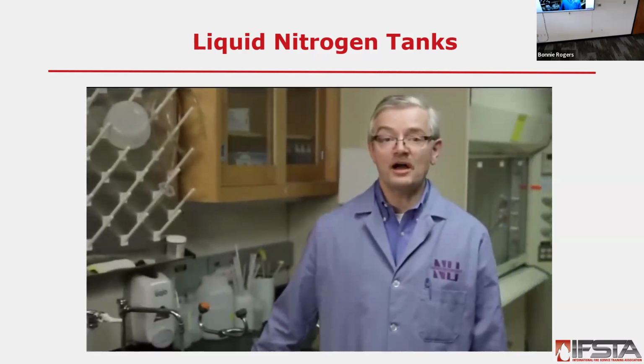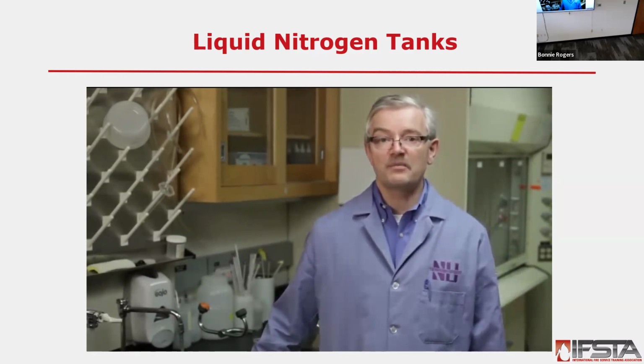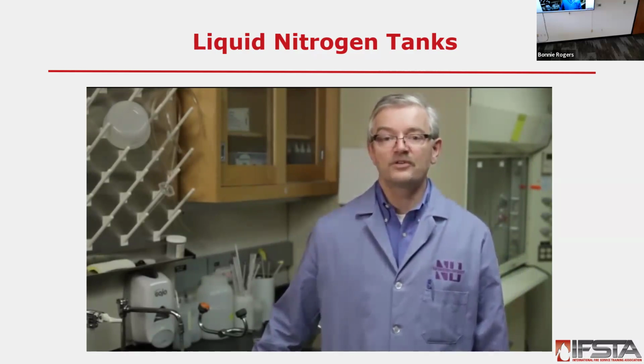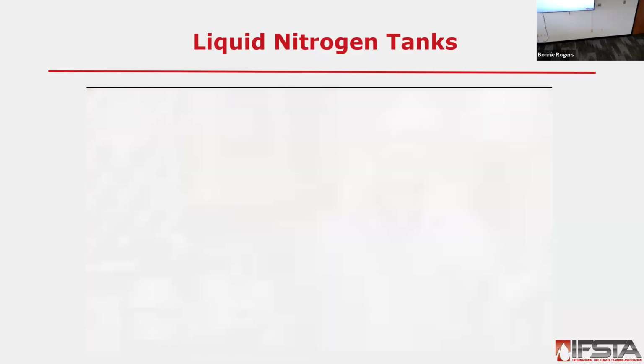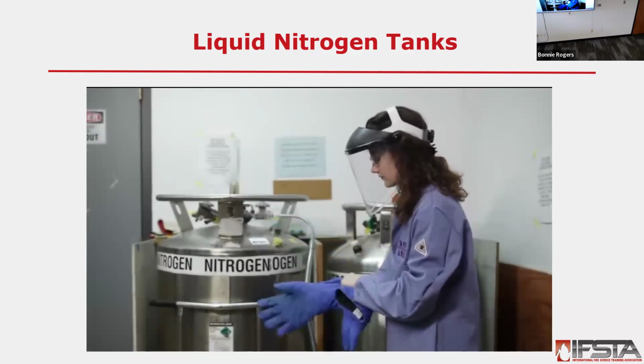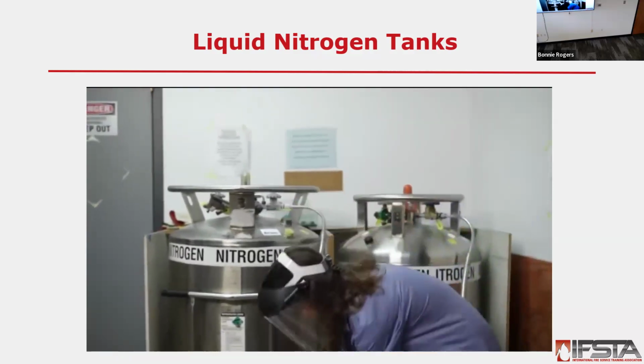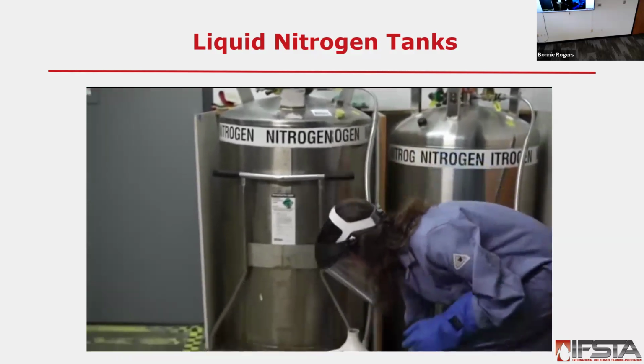Operators should never block, plug, or attempt to repair anything on a liquid nitrogen tank containing liquid. For assistance, contact the university staff member responsible for the liquid nitrogen facility. Always wear appropriate personal protective equipment before withdrawing liquid nitrogen from a tank or withdrawing cryotubes.